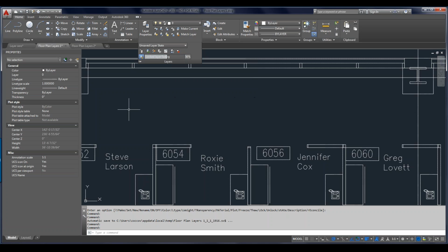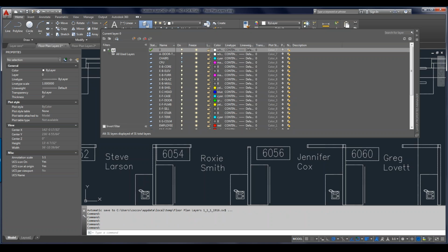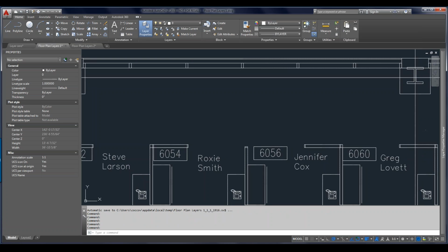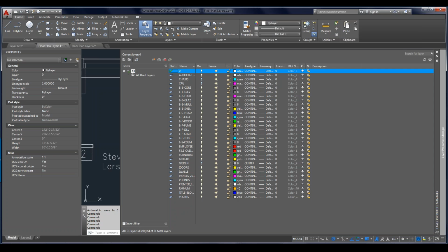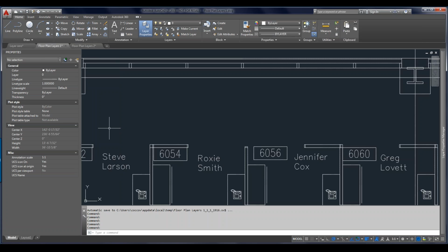Okay, yeah, no problem. All palettes are going to have that function in AutoCAD. In the properties palette here, when to use it, how, I can't tell you that. That's a working preference. If I do use it, I like putting it into an allow docking mode, and then typically I would go ahead and anchor this to the right, and that way it's always there, and as soon as I move off of it, it goes into an auto hide mode.